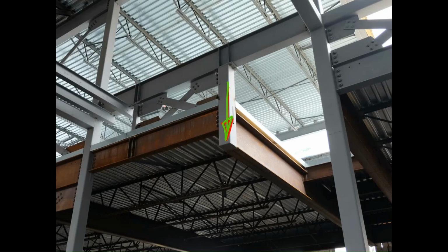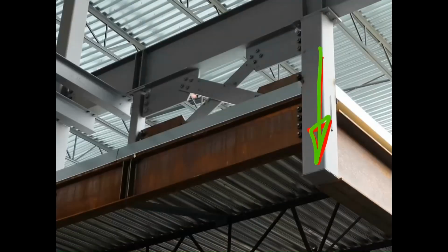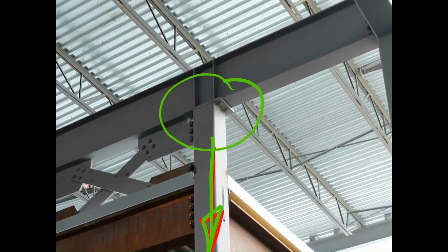In this case, I'll zoom in a little bit. We've got these 4 bolts up here, and those are going to be carrying that tension force directly through tension in those bolts because we're pulling down on the hex head. We're transferring force longitudinal to the line of the bolts. So in that case, those bolts are actually going to be carrying the load in tension.